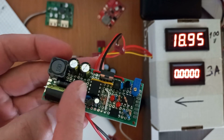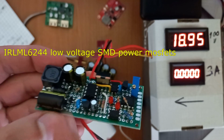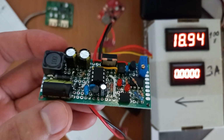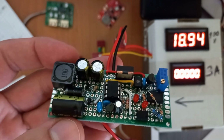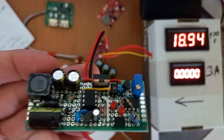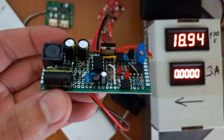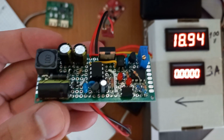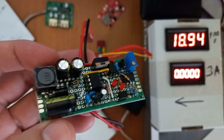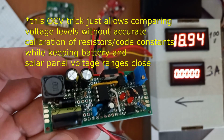This newest prototype has SMD power MOSFETs, which are very good. I can recommend it. This latest prototype is apparently the most efficient solar power bank charger in the world at the moment. It charges a lithium-ion battery directly with 90+% conversion efficiency, uses no shunts, no input or output diodes, and still doesn't have reverse current. This is achieved via a special trick based on OCV measuring. That feature was recently added to the project.